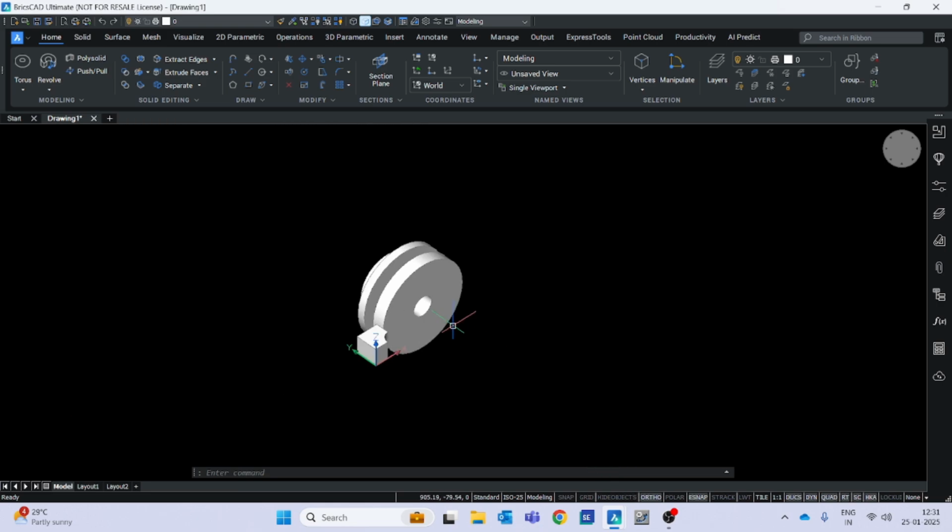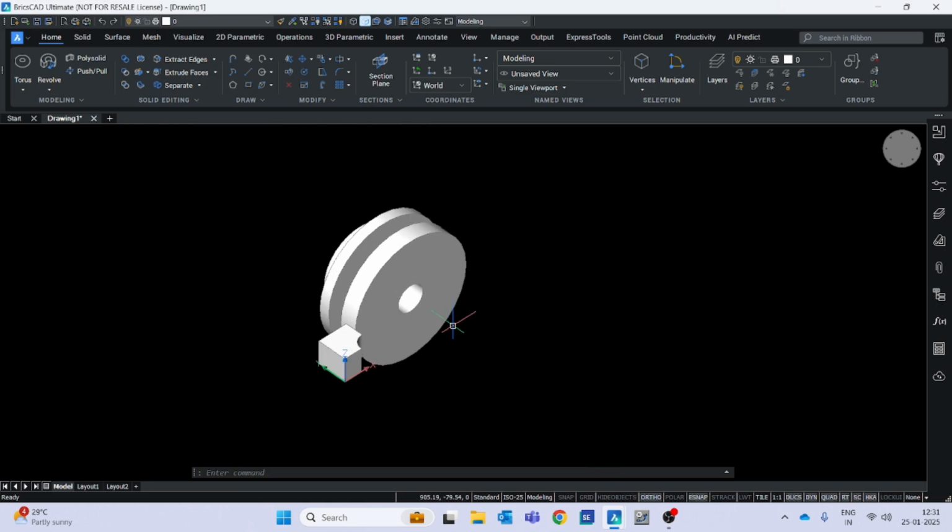So the next thing is we are all set with the basic primitive tool sets, and also our extrude cuts and revolve features. But if I need to draw in a specific plane, or shift to another plane, we can make use of our UCS settings. So let us go and explore the same.